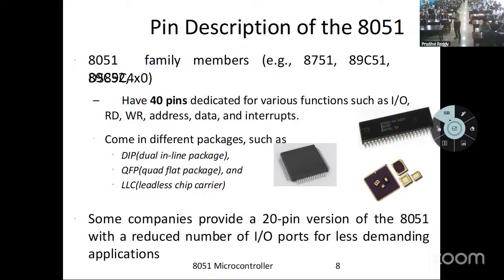Now the dual in-line package means 20 pins here and 20 pins here, so the vertical shape is increasing. If you want to use only this size, you can put 10 pins on each of the 4 sides, 40 in total. If the pins are arranged on 4 sides of the integrated circuit, that is called the quad flat package, QFP.